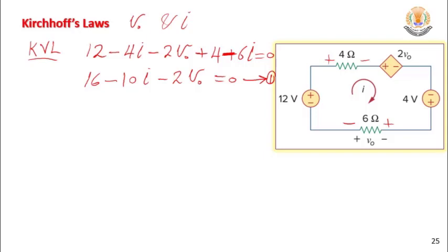If you look at V naught here, V naught, Ohm's law, look here please, equals what? Minus. Why? Because polarities are opposite, the red one which I wrote and the original one. Do you agree? So here it will be minus 6I. This is equation number 2.